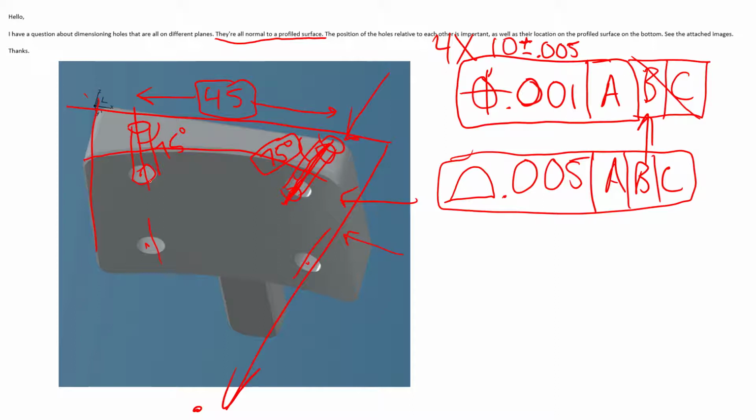But once again, all we're doing when we're setting up datum reference frames is we're setting up, all right, in a perfect world, this is what it would look like. Or in my CAD world, this is what it would look like. But then this is the error from the perfect world. This is the error that the axis would actually be. It could be angled or it could be out of position, both of those, orientation and location in here. How far it could be from that true location.